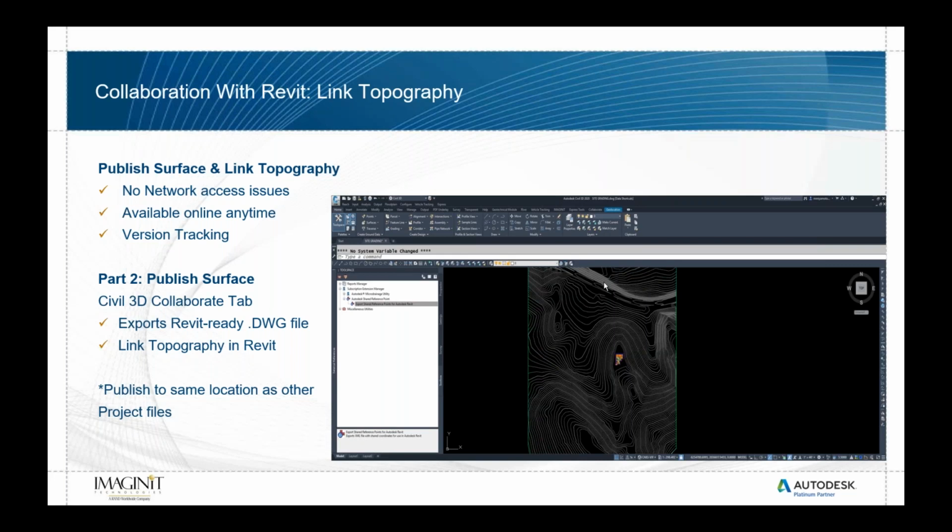If you skip the process of doing a shared coordinate and you're just trying to import the surface and link it to Revit or create a surface manually, there's a lot of estimating and moving and eyeballing the location and moving it up and down or left and right. But if you are able to publish that surface out, it's a true XYZ coordinate coming from Civil 3D that's being assigned to the corner of the building. And then when the surface gets published out, it's going to link that same XYZ from the surface into that bottom corner of the building. So it will automatically place the surface underneath the building where it's supposed to be.